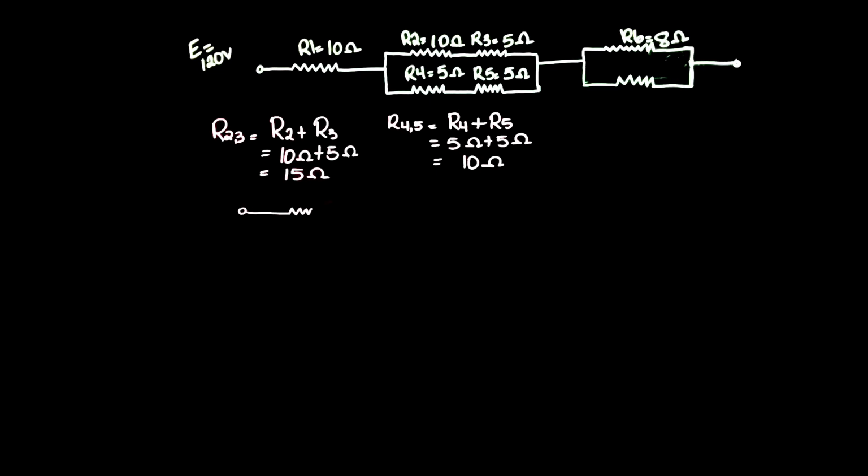So when you're finding the resistance total of a series parallel resistive circuit, it's all about reduction, and reduction in the correct order, until we end up with a series circuit. So R1 will be brought down exactly as shown. My R2,3 now has been brought together. My R4,5 has been brought together. So I will redraw it in that manner. And then resistor 6 is untouched.